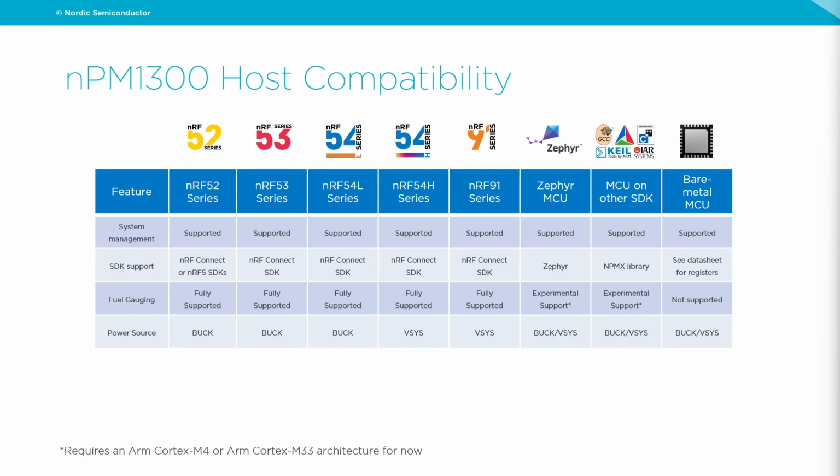So which SoCs are compatible with the NPM 1300 PMIC? Well, any MCU that you can find with I2C is supported with the system management features and all the power regulation features. So battery charging, buck regulation, and the different recovery features are all supported on any I2C enabled master device. For the nRF52, 53, 54, and 91 series devices, this is achieved through the nRF Connect SDK normally.